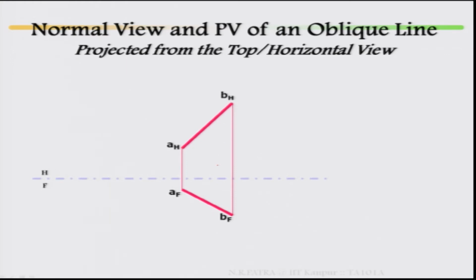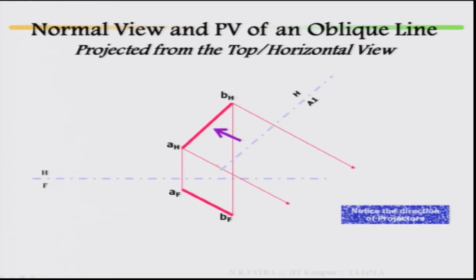In the horizontal plane, AH and BH, top view, then the line of sight, step 1, then draw your auxiliary plane, step 2, at any distance. Then draw the lines of the projections, then measure the distance in your opposite view, in your front view from your hinge line, then relocate the same distance in your auxiliary plane.